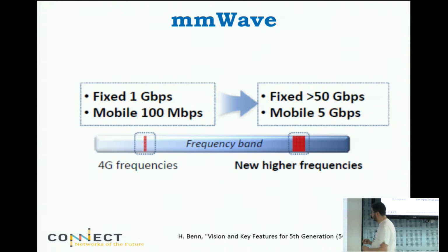I want to quickly go through again the technologies that are of relevance to 5G. If you focus, for example, on the spectrum category of increase to the capacity I was mentioning before, millimeter wave is a very natural choice. There is a lot of fallow spectrum if you go high up in frequency. High up, I mean, roughly speaking, beyond 28 gigahertz. It depends on the definition, but definitely at least an order of magnitude higher carrier frequencies than we are used to. Normally we work around 2 to 3 gigahertz.